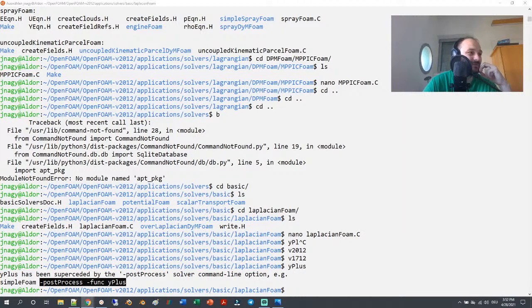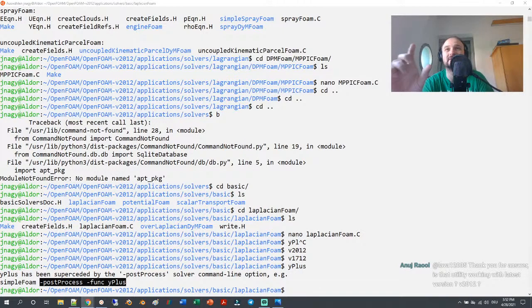Could you do a small explanation of using extrudeMesh? Well, this is a longer topic, so I usually draw the mesh in Blender and then export it as an object file and then just extrude it with, I don't know, with the mean cell edge length. So this is what I usually do.